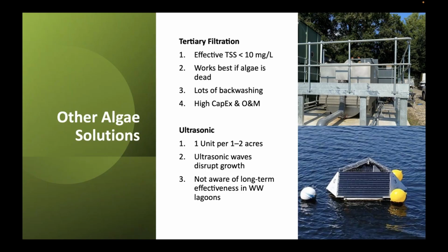It really works best when you kill the algae first, and then it's easier to filter it out. But I would say the biggest downside to me is it's CapEx, man, and it's OpEx too. You have to spend the money to put it in, and you've got to maintain it. And I haven't seen a lot of lagoons be really good at maintaining these types of mechanical pieces of equipment. So in that respect, I wouldn't recommend it for an algae solution. If you're trying to meet a low phosphorus limit, sure, absolutely. But just for algae, I wouldn't recommend a filter.